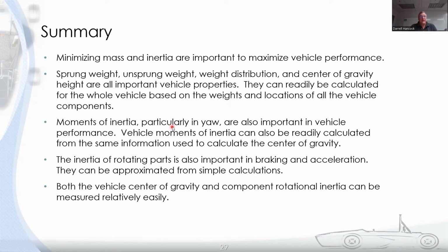Moments of inertia, again, particularly in yaw, are important in the handling of your vehicle. You can, again, calculate them pretty well from basically the same information you use to do your center of gravity calculations. A little bit harder to measure the yaw moment of inertia of your vehicle. It can be done, and using a trifilar pendulum is not the only way to do that.